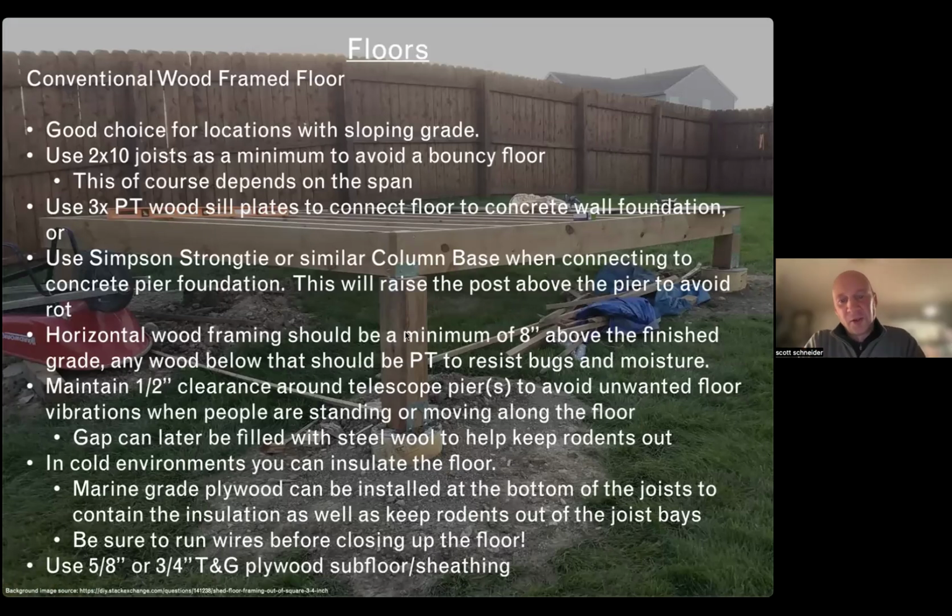Yeah, so I think in all situations except for maybe a mat slab, you'd want to separate and do separate pours. And normally a half inch is probably good all the way around the pier. If you have a wood frame floor floating above, with the concrete sticking up through it, you can put steel wool or something like that in the joint in between to keep bugs and rodents out.